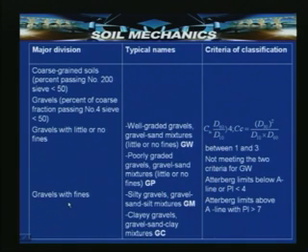Gravels with fines, that is silty gravels, gravel sand silt mixtures, is called GM if Atterberg limits fall below A line. That means, as we have just discussed, if the plasticity index is less than 4 and it is falling below A line, then it is called GM. M indicates the presence of silt, but a low plastic silt. That is why it is falling below the A line.